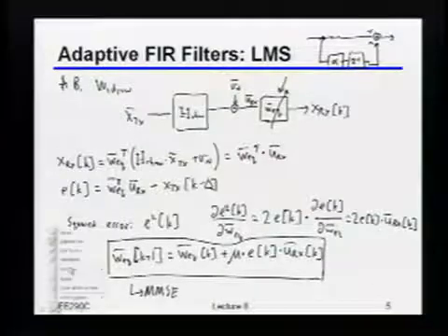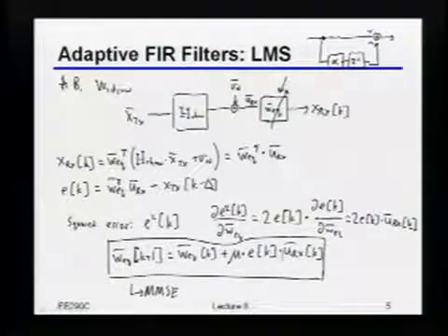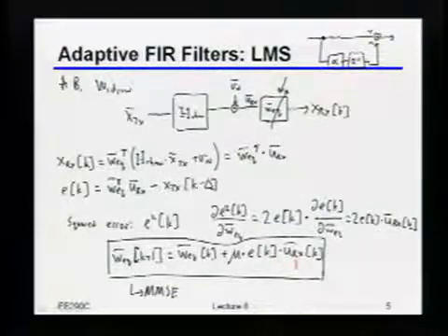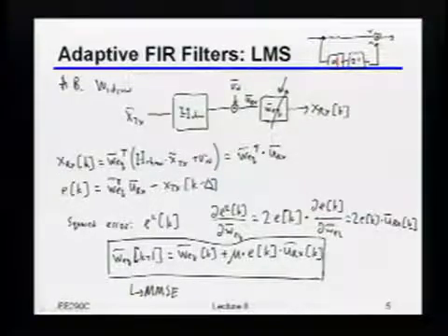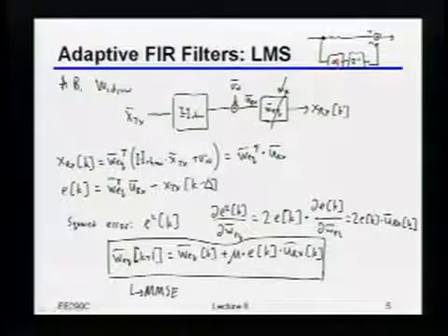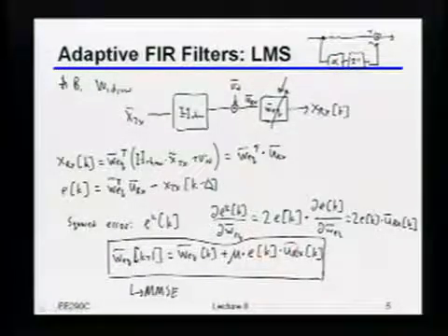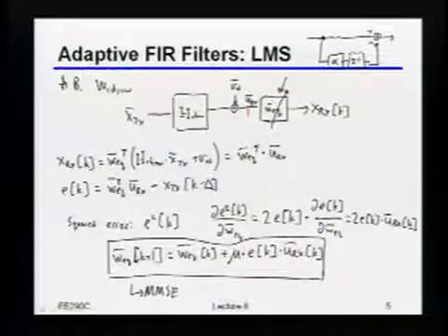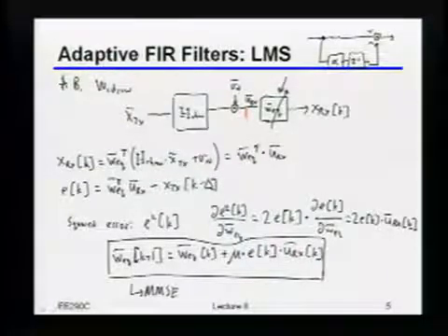So when I do this update equation over here, I really just have one coefficient, right? The coefficient I have is basically, what is this alpha value? But in order to find that alpha value, what I really have to do is correlate the current error with essentially what came into the equalizer 1 bit ago. Does that make sense now?